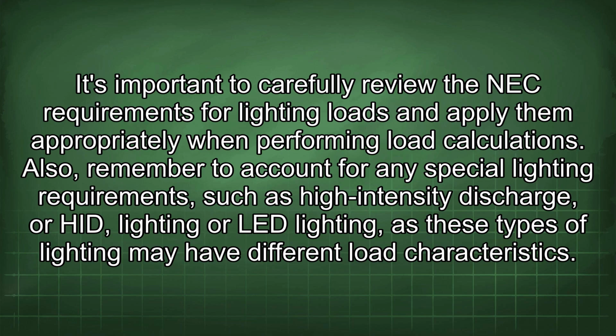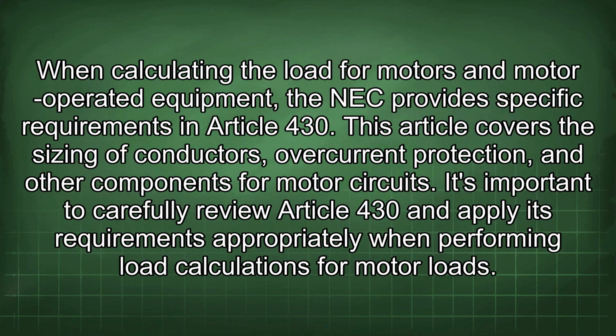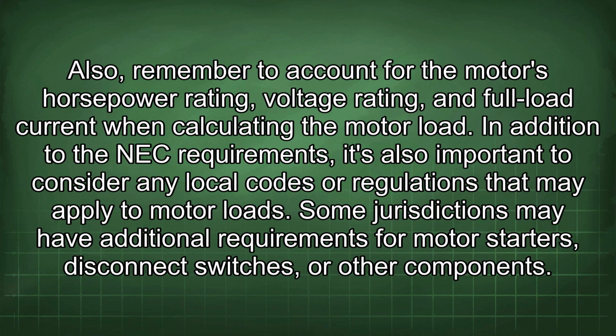these types of lighting may have different load characteristics. When calculating the load for motors and motor-operated equipment, the NEC provides specific requirements in Article 430. This article covers the sizing of conductors, overcurrent protection, and other components for motor circuits. It's important to carefully review Article 430 and apply its requirements appropriately when performing load calculations for motor loads. Also, remember to account for the motor's horsepower rating, voltage rating, and full load current when calculating the motor load.